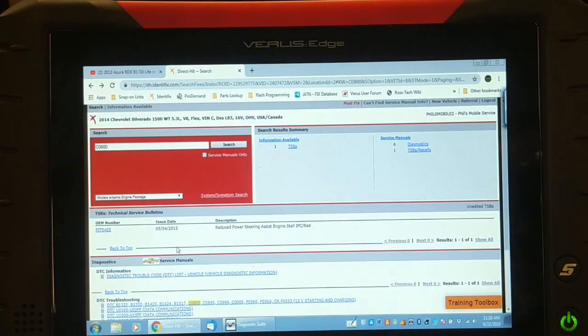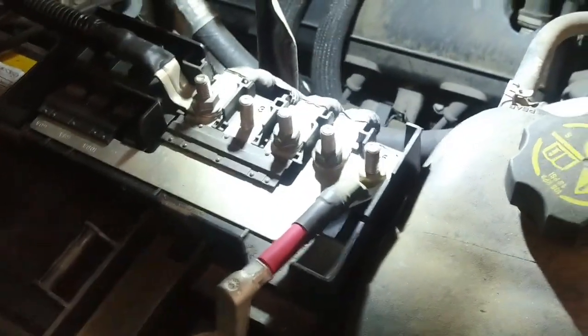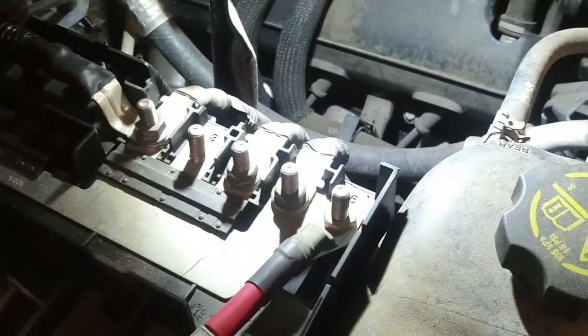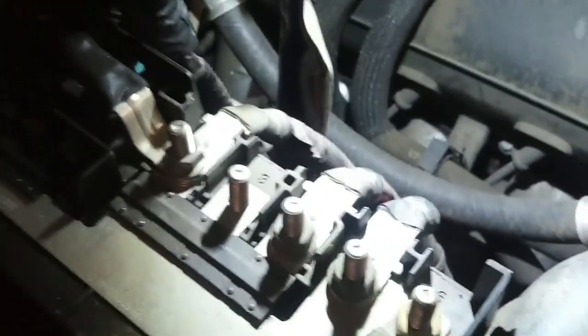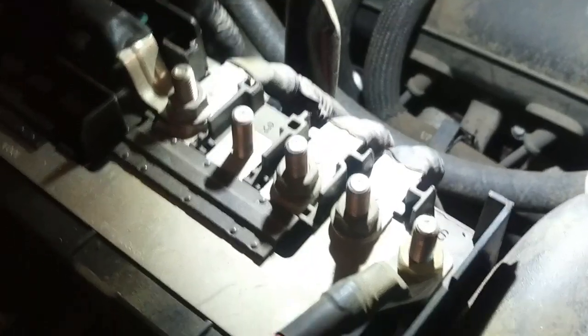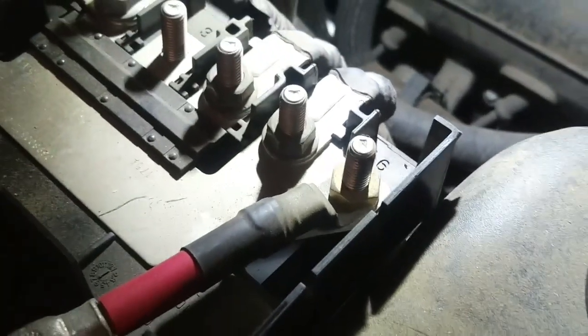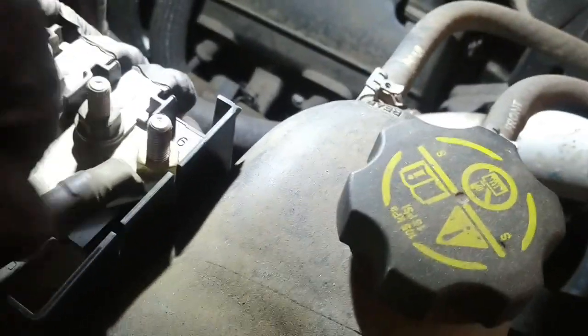Well, I'm going to do a little bit more searching off camera. So I took the brace bar off the fender here so I could access this electrical center above the battery. I've checked the battery cables. Both cables appear to be clean and tight. I've checked this harness connector. I'm not sure what those two heavy red wires are for, but they are clean. I put some dielectric grease on. All these bolts are tight.